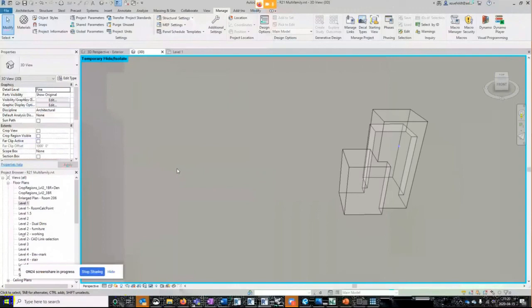Good to know. And the second question is, an issue started in 2020 where if you have a system family, either a floor, ceiling, or topo that has curves and you mirror the plan, then if you need to make edits to those components with the curves, you will be unable to draw in correctly. That's something I'm not actually familiar with. So it's not good to hear, but it's good to know about that.